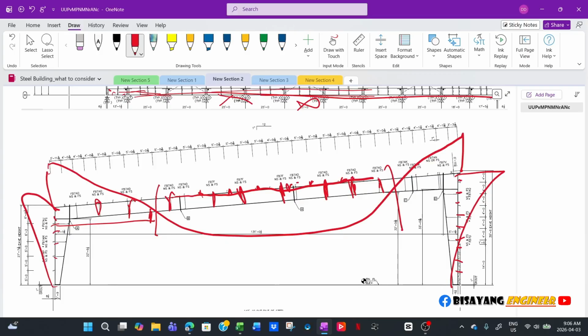That braces your frame against torsional buckling, because if the unsupported length exceeds the limit, then it will significantly reduce your capacity, because once it considers the lateral torsional buckling, it will significantly reduce your capacity. So in this region where your compression is at the bottom, bracing is really important right here.